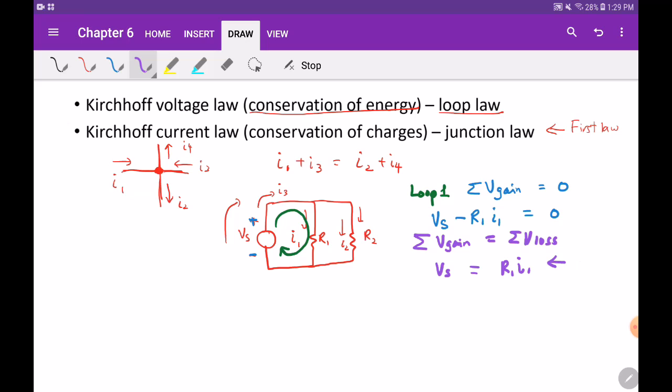When you write the voltage drop, what people do is they put a terminal here, and you indicate positive, negative. So this will be, let's say, V1, which is also equal to V2. V1 is the voltage drop across resistor 1, and V2 is the voltage drop across resistor 2. Since they're parallel, they're the same. And this V1 becomes a drop because of the way we write the plus and minus. We put the plus in the opposite direction of the voltage source. Let's take a little break, and I'll see you in the next video.